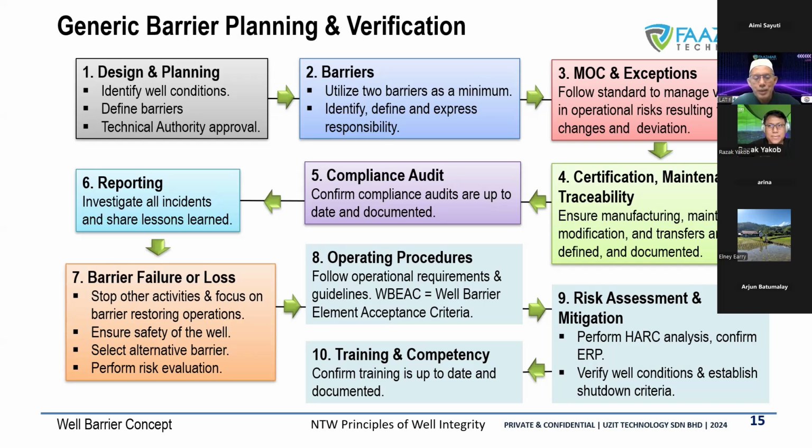So it depends on how much flexibility we have to have the option of barrier by well, rather than one barrier, one well failed, and everything is shut down. In terms of our experience, normally we see that some of the incidents can be handled on a well to well basis, so you don't need to have a shutdown. But in most cases, like a small platform, our simultaneous operation system and management system contingency plan is quite limited. So one well failure will cause the full shutdown of the platform.